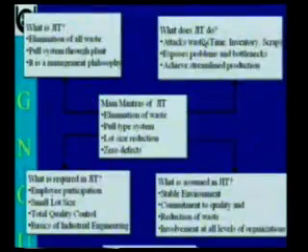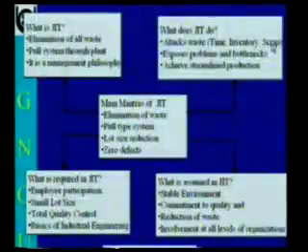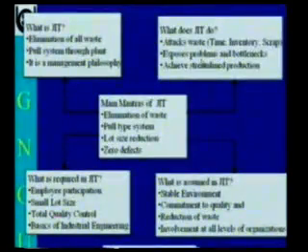Now what does JIT do? JIT attacks waste: waste in terms of time, waste in terms of inventory, waste in terms of scrap. It exposes the problem. By keeping excess inventory, you are hiding the problems. But with JIT, when the inventory is low, you are exposing the problems and bottlenecks, whether in terms of defects, parts, or any other type of bottleneck that comes into the picture, and that is going to be removed in JIT. It achieves streamlined production.